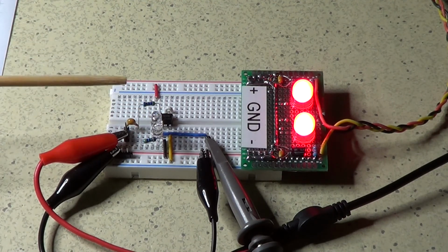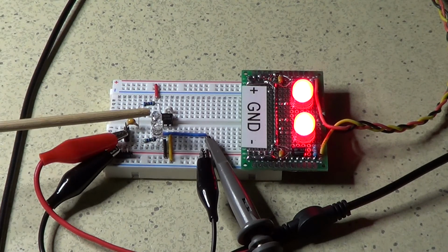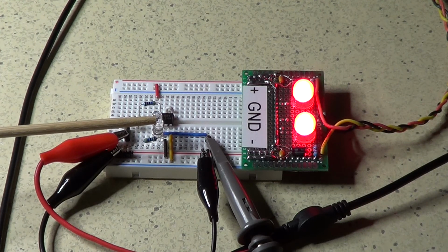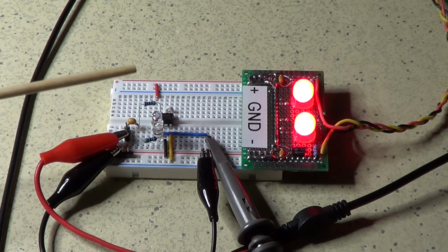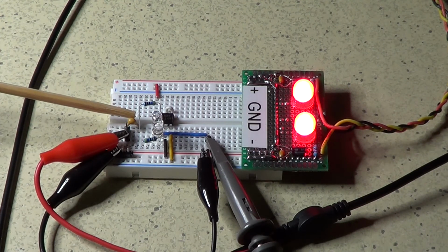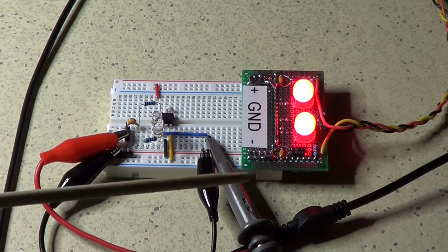These are the two resistors that set the gain for small signals to 1, and here are the two LEDs that are put in parallel with R2, but with opposite polarization between each other. And this is the input capacitor, which removes the DC component from the input signal. To test this circuit, I have connected its input to these two alligator clips that go through the cable to